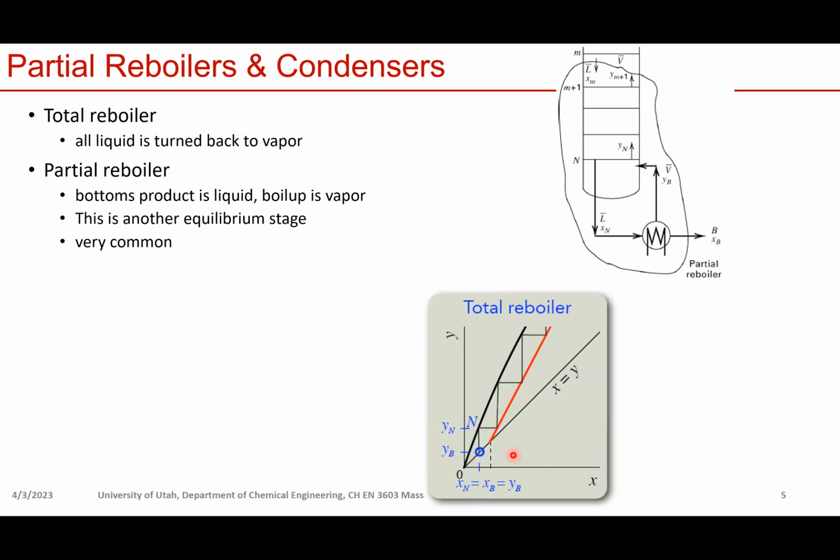In this case, we can see that the operating line crosses a point that now has a higher mole fraction than the reboiler. So you can achieve your desired separation outcome, but you don't fully utilize the capacity of your distillation column. Ideally, this point overlaps with this point. Then you can maximize utilization of your distillation column.